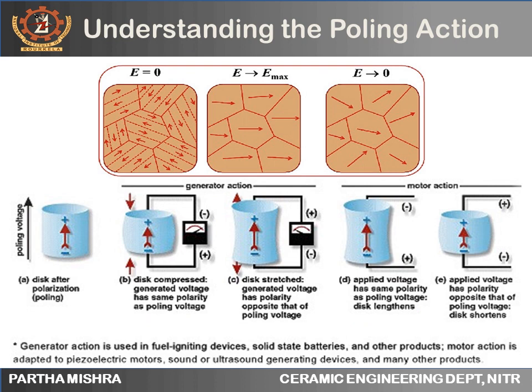Now, what is electric poling? The electric poling action implies the alignment of the dipoles present in the cubic system of the PZT when an electric field is applied and the temperature is raised above the Curie temperature. But why is increasing the temperature not enough? Why do we need to apply an electric field? The problem is that we cannot gain a good polarization even if the temperature of the crystal is above the Curie temperature, as these PZTs are polycrystalline, and unlike single crystals, they can only align up to an extent within their domains.